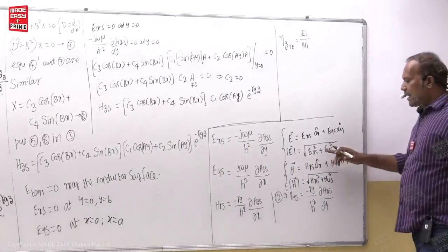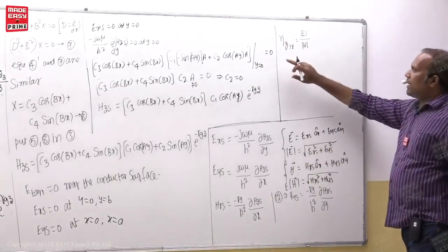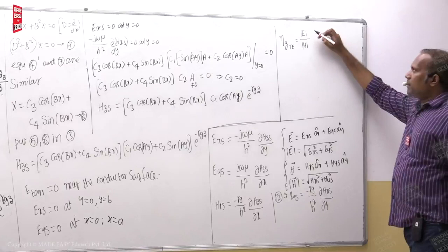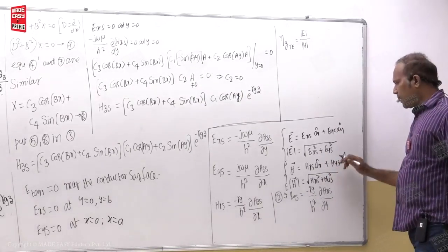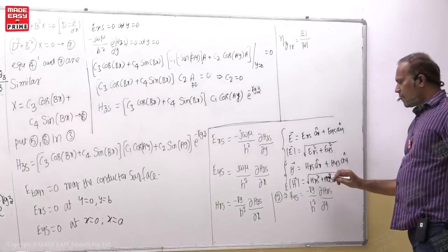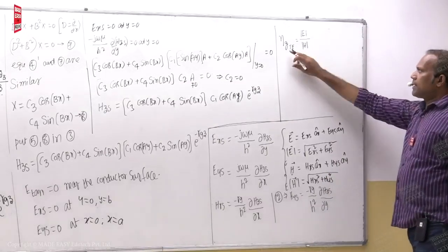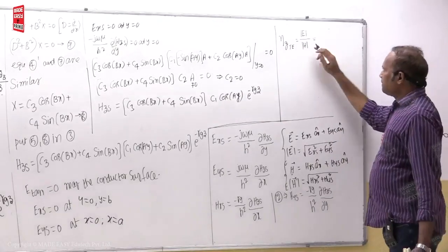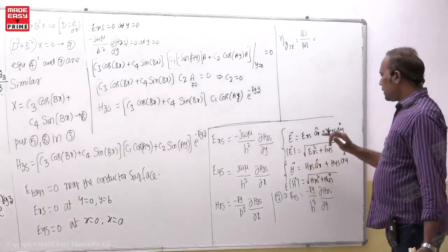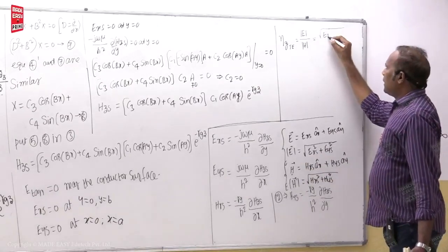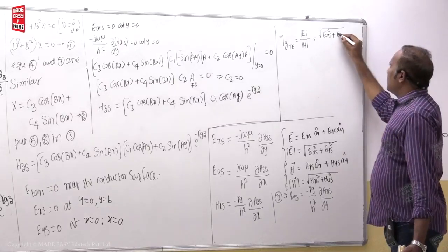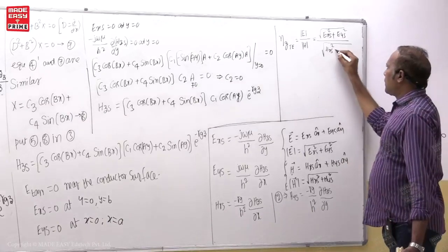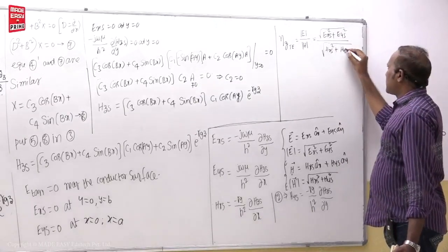They start interchanging with each other. That interchanging happens because of eta. So eta gives a relation between E and H. Whichever components generate each other, for example, electric field x component generates magnetic field y component, electric field y component generates magnetic field x component, they only interchange the energies or powers through the intrinsic impedance. So now from this, if you write here, the modulus of electric field is root of EXS square plus EYS square, divided by this one, root of HXS square plus HYS square.